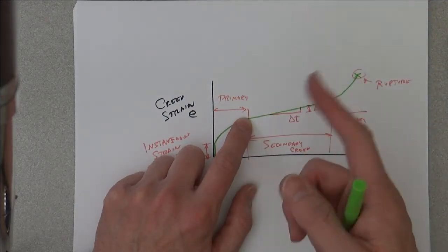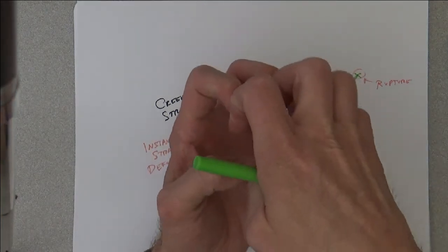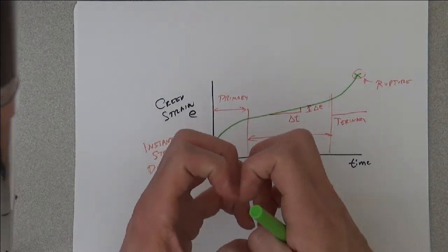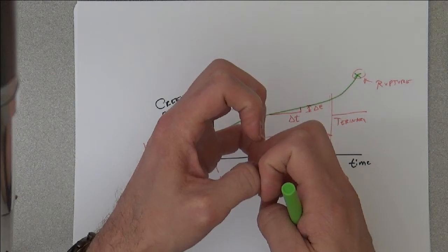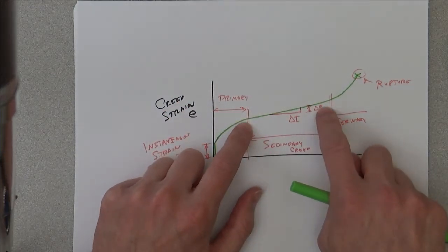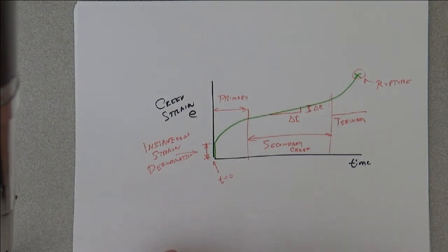You might also have, for example, some type of grain boundary sliding in which these grains in this region start getting themselves aligned, and then in this region, the grains are able to slide past each other very slowly. And again, the grain boundary sliding is assisted by defects.